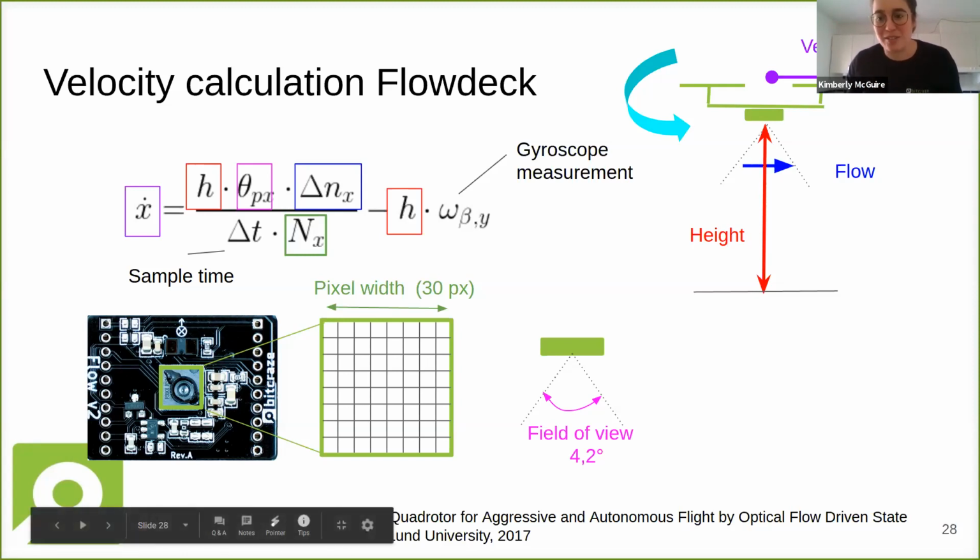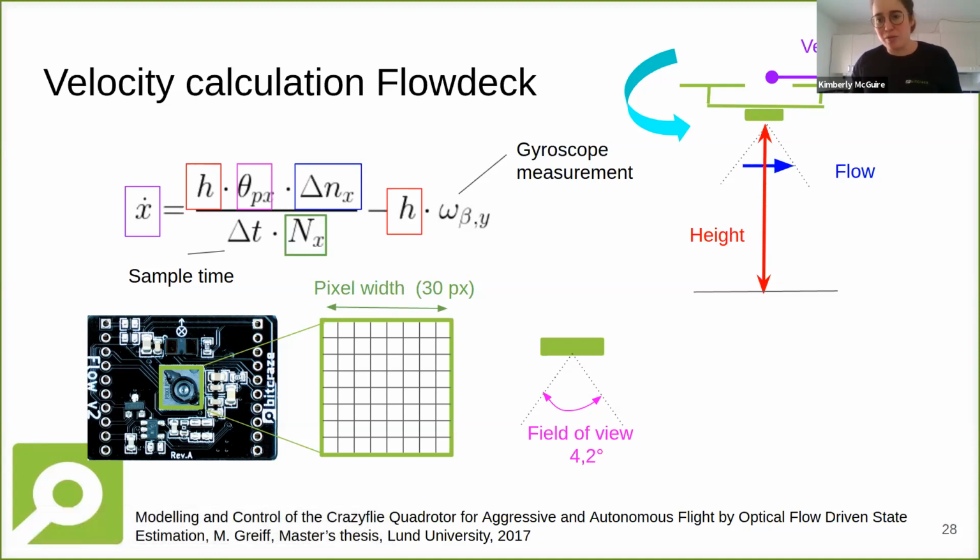Why not subtract it? Isaac, are you referring to the rotation around yaw? Yeah, good question. The person that implemented this assumes that the angle will be so small that it's not going to have that much effect. But I actually found out during my research that the Crazyflie I was using was yawing quite a bit. So I would have liked to see it subtracted, yes.